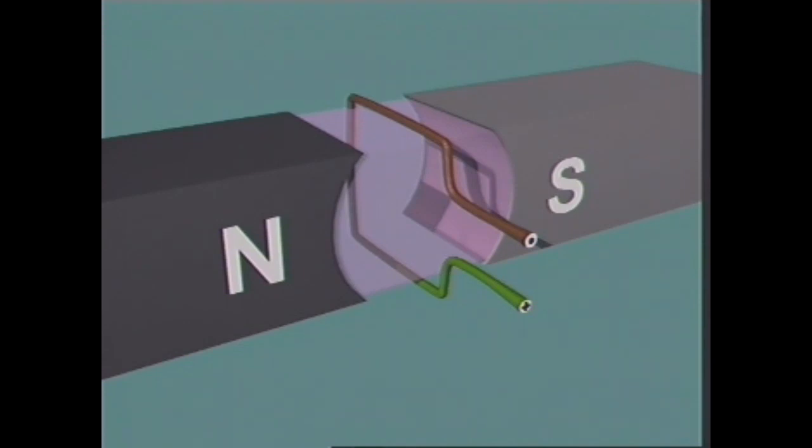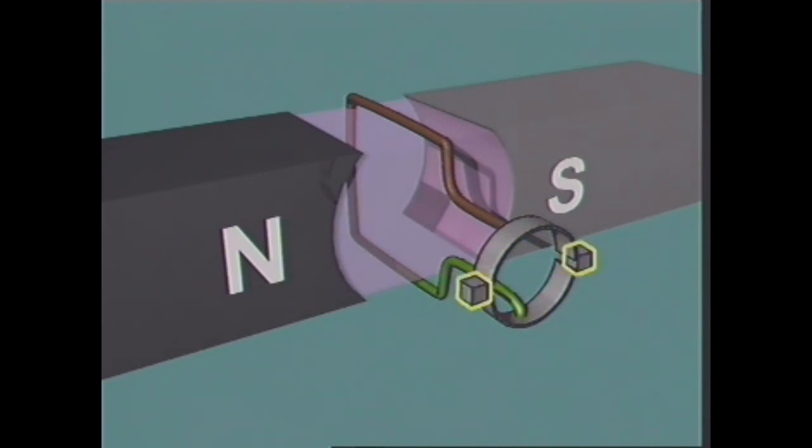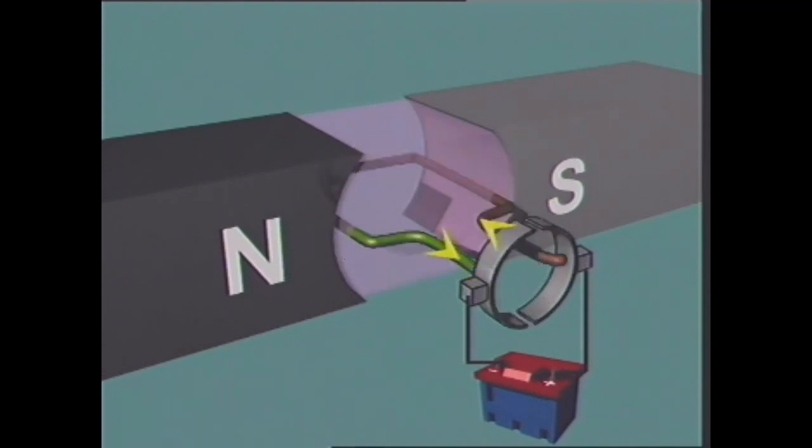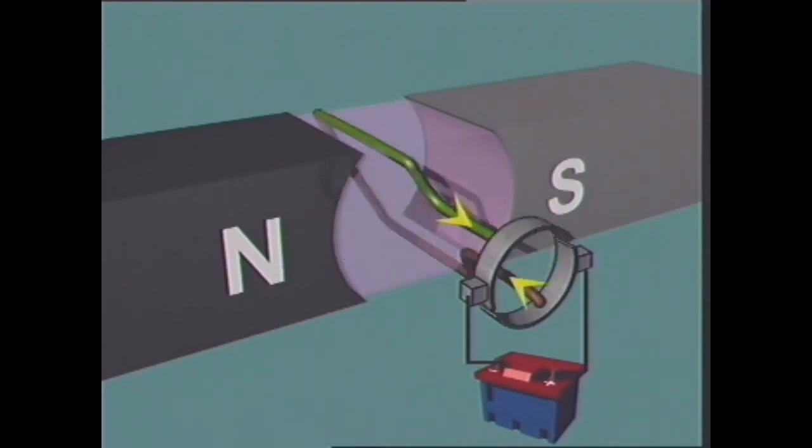To continue rotation, the direction of current flow in the conductor must be reversed at this static neutral point. A commutator is used for this purpose. In this example, the commutator consists of two semicircular segments which are connected to the two ends of the loop and are insulated from each other. Carbon-impregnated brushes provide a sliding connection to the commutator to complete the circuit and allow current to flow through the loop. Rotation commences with both sides of the conductor loop cutting the stationary field.